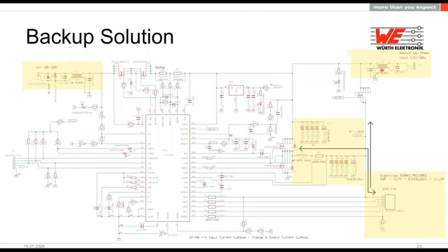Because the IC works in boost mode when the supply voltage is down, we need some filter at the output side. Also, the output and input capacitors are important to have a good signal and low ripple voltage. This is here, input and output capacitor. And here in the right corner, our supercapacitor bank is connected via some terminal blocks.